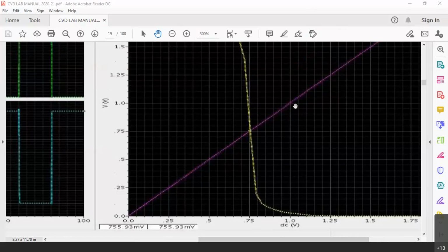So here, if W increases, drain current increases. So we cannot change L. In general, we don't make any changes to the channel length because channel length is fixed. Channel length we fix at 180 nanometer here. So now you can increase the W of the P MOSFET. If you increase the W, the P MOSFET will become as fast as the N MOSFET.